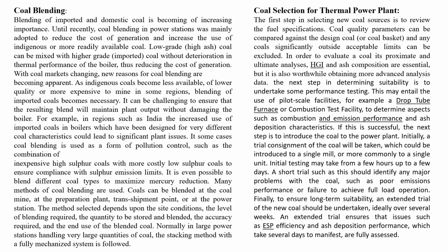Nowadays blending is a must because of the cost price, and also the design of the furnace is such that you cannot burn the higher grade of coal in India. So blending is an essential factor in thermal power plants or coal handling plants.